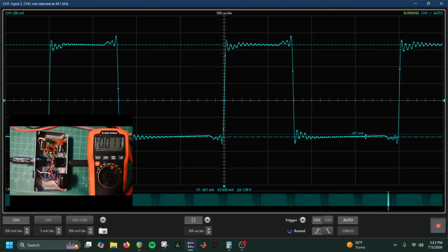So if we were just doing, let's say, symmetric clipping, where we had 660 millivolts here and 660 millivolts here, that is actually just going to generate odd-ordered harmonics. So if we were to normalize this 500 hertz sine wave to 1 hertz, we would see harmonics at 3 hertz and 5 hertz and 7 hertz and 9 hertz and so on. So that's that hard distortion sound.